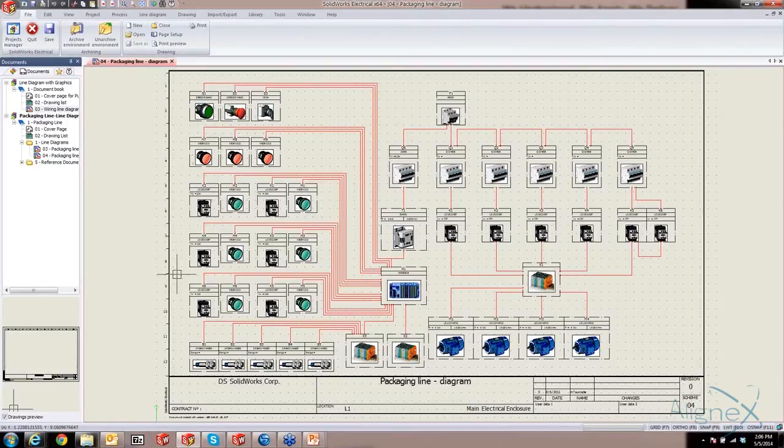Now what we're really doing here is laying out, in a very generic line format, that inside of this cabinet, or coming into this cabinet, are these 4 motors down here. So there will be cables that connect directly into the terminal strip. Someone at a high level, whether they're at a managerial level or just someone who needs to quickly understand what's happening with the electrical scheme, can look at this single line diagram and relatively quickly understand where things are going and how they need to connect.